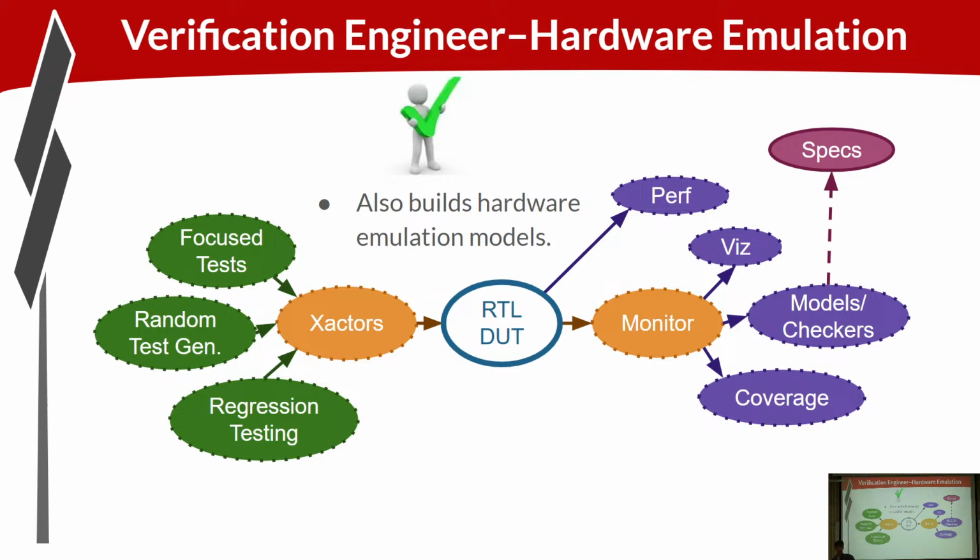There's a large push right now to make those two environments more compatible with each other. TL-Verilog potentially plays a very important role, since TL-Verilog is modeling things at a more abstract level. The modeling methodology of TL-Verilog is more appropriate for performance modeling than RTL would be. If you model these components, the transactor and the monitor, using transaction level Verilog, you're naturally synthesizable. So you can fit these components on the FPGA as well, and thereby not limit the performance that you can get for hardware emulation.